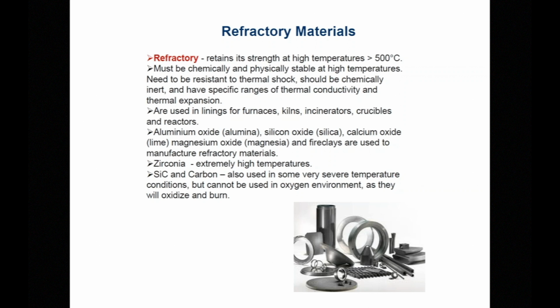If you go to the lab and look for your high temperature oven or crucibles or different types of high temperature reactors that can go beyond 1000 degrees C, you will see linings of ceramics on the side of those ovens or vessels made up of this high temperature resistant or poorly temperature conducting refractory materials. So this would include compositions based on aluminum oxide, silicon oxide, calcium oxide, okay, fire clays, etc.